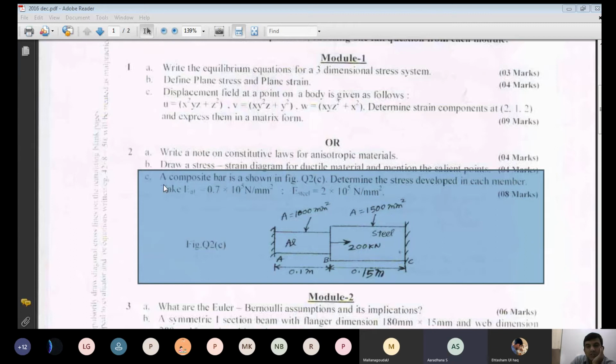Yes, sir, following. Now how many unknowns are there? P1 and P2 are unknowns; 2 unknowns are there. We have only one equation. What is that equation? The vector sum of all the forces acting in the horizontal direction is equal to 0. What is the one more equation? Remember, for statically indeterminate or compound bars we have two equations. One is by applying the static force equilibrium equation. What is the second one? Anybody can give the answer.